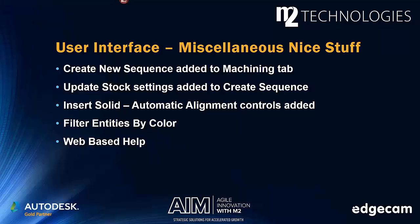Additionally, there are cases where we may want to create a secondary sequence, maybe make an alternate routing or some minor adjustments to rework a part or something like that. And we really don't need the relational setup and just want to make a quick setup on the fly. We don't need to really do a whole new setup. Well, the new sequence is convenient there too. Additionally, when you create a sequence, the update stock settings are now available on the third page of the create sequence dialog. So this allows you to set some parameters for your preferences for how the background update stock settings should work on the part.